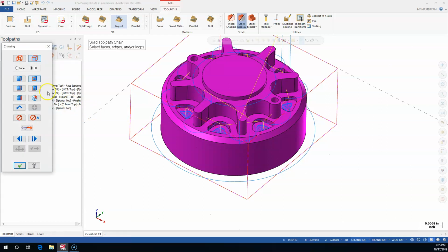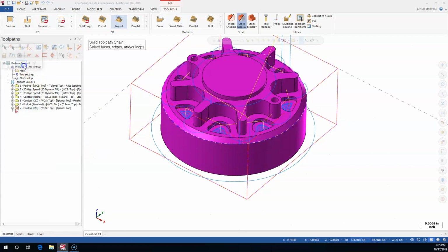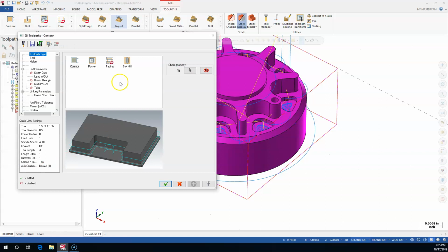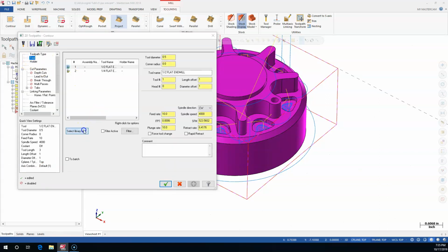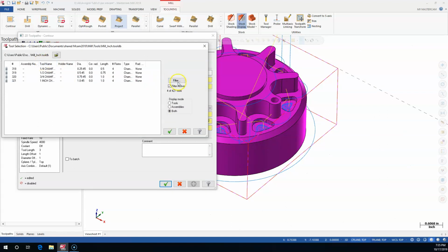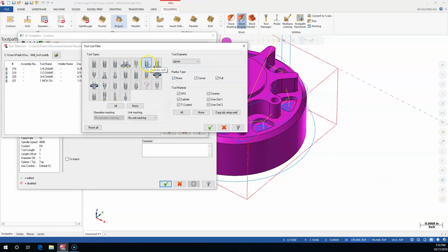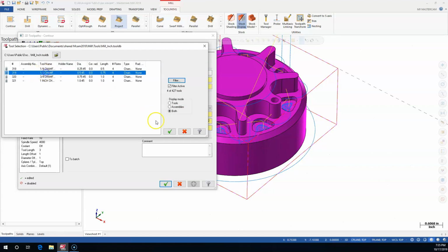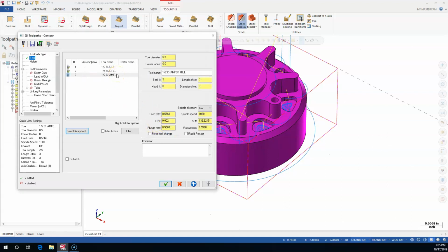Let's go to the chamfer. And so for our chaining, I'm always a little confused whether I should pick the top or the bottom. Let's go with the bottom, and we'll accept, and we'll see what we get as a result. So the tool goes to select library. Jumped right into our filter. So filter would be for the chamfer mill. We'll go to 1/2 inch. And spindle speed 2000 RPM. Feed rate can be about 10, and we'll stay with 10. Rapid retract. Set up our chamfer.